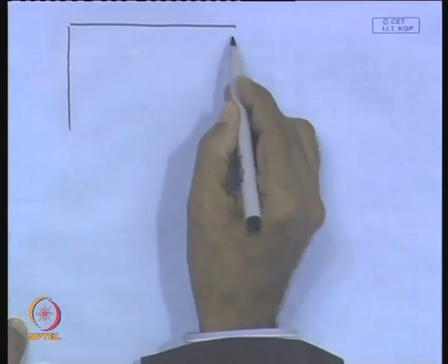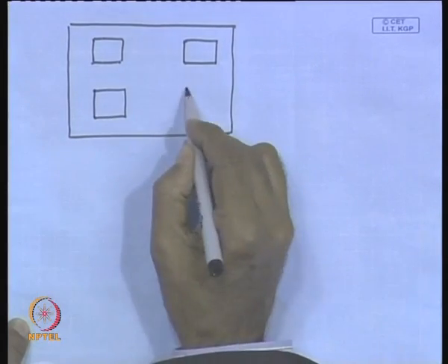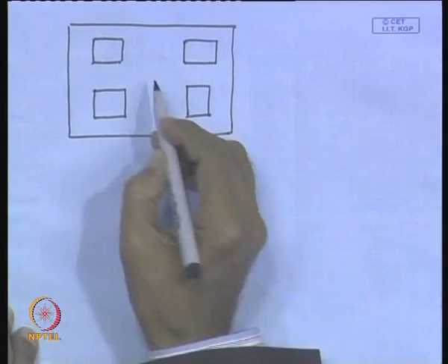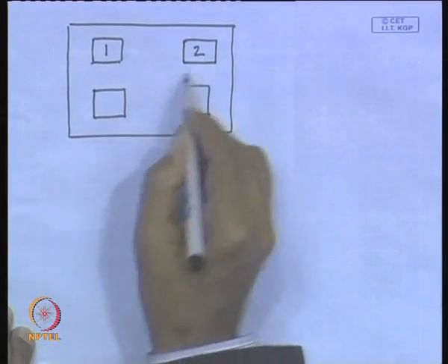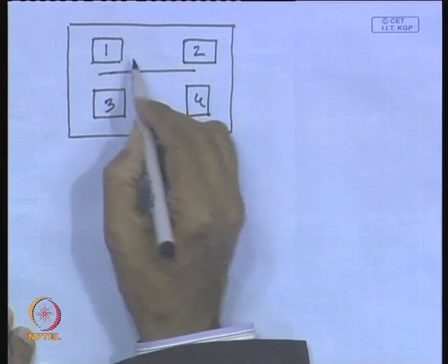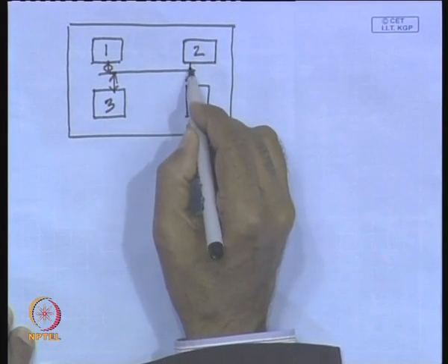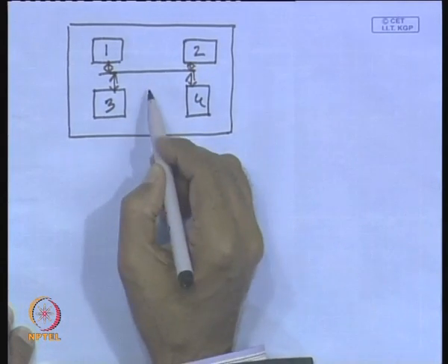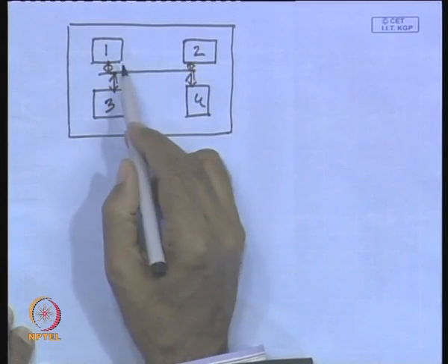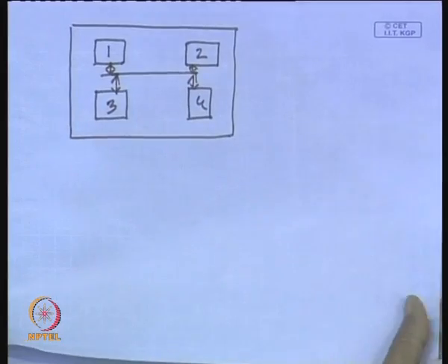In a single chip, you can have a number of different subsystems. So, this can be one subsystem, this can be one subsystem, or it can be a multi-core. In such a case, these subsystems may communicate with other subsystems, and you can have a common bus through which communication may be done. That means these are all connected to the bus. Another alternative is that you can put a switch through which they can communicate. Whatever the case, whenever it is going out from one subsystem to another subsystem, the same problem will arise, that means capacitance will be large.